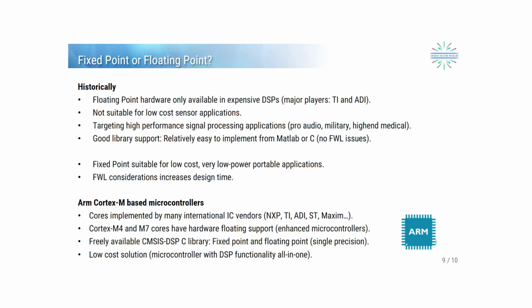Nevertheless, the good library support and ease of implementation from MATLAB or C was certainly attractive to many. Fixed point, on the other hand, was and still is intended for low power and low cost portable applications. However, the design time needed was significantly higher due to the limitation of fixed point arithmetic on the algorithmic performance.